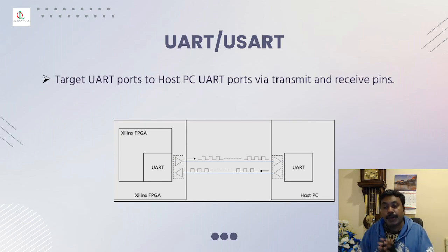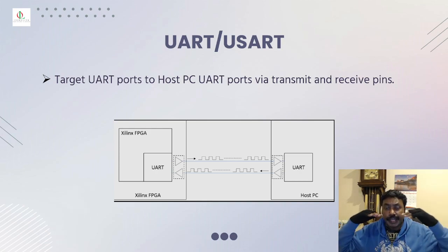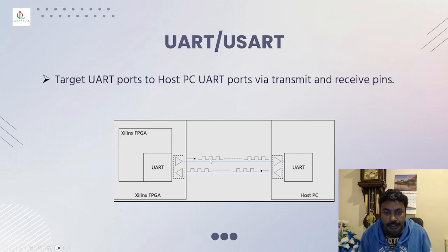When we talk about communication transmission, the one main thing is you have to maintain those two USART pins on the same speed, in other words, the same baud rate. What is baud rate? As you all might know, baud rate is nothing but transferring data bits per second.